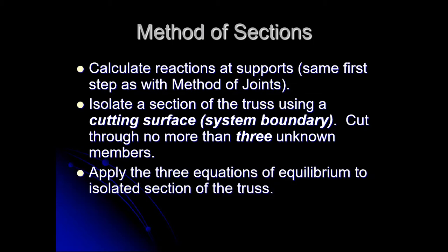So with our section of the truss isolated, what we've really got is a non-concurrent force problem. And in a non-concurrent force problem, we had 3 equations of equilibrium. The sum of forces in the x direction equals 0. The sum of forces in the y direction equals 0.